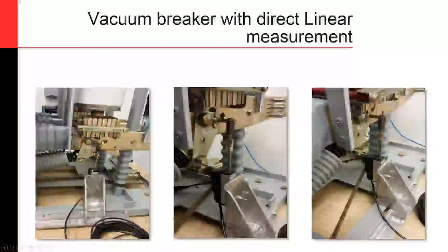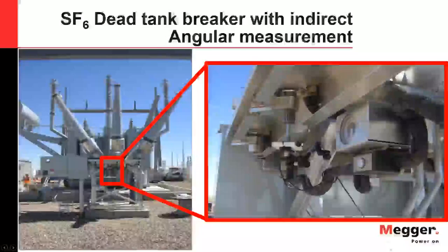This is an example of a vacuum circuit breaker where now we have this little direct connection down on the right below one of the poles. So this is on the outside leg there. So once again, it's gang operated, but this manufacturer puts this little tab so you can hook directly to it, and as that vacuum bottle actuates up and down, your transducer will go up and down, and you're getting the exact stroke of that vacuum bottle there.